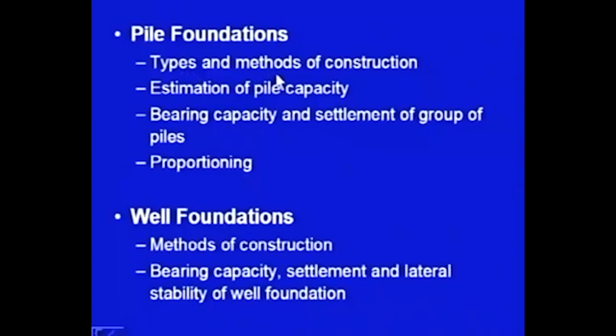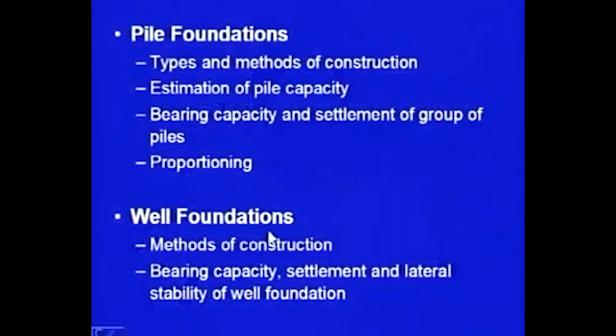Here we shall start with the types and methods of the pile foundations, then how to estimate the pile capacity from the soil design parameters, from the tests which we have already done in the field or in the laboratory, then how to calculate the bearing capacity and settlement of a group of piles, and finally how to solve the design problem. Proportioning means we are basically designing the actual pile foundation.